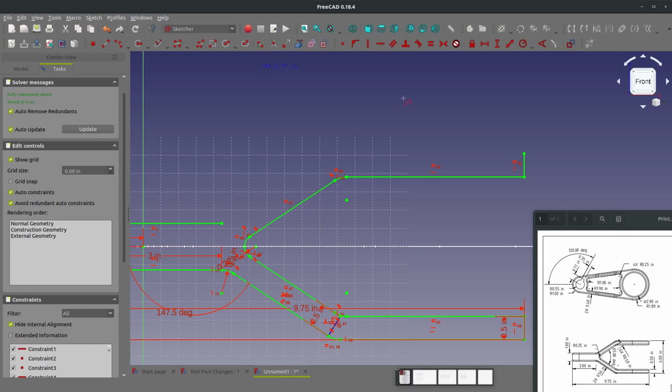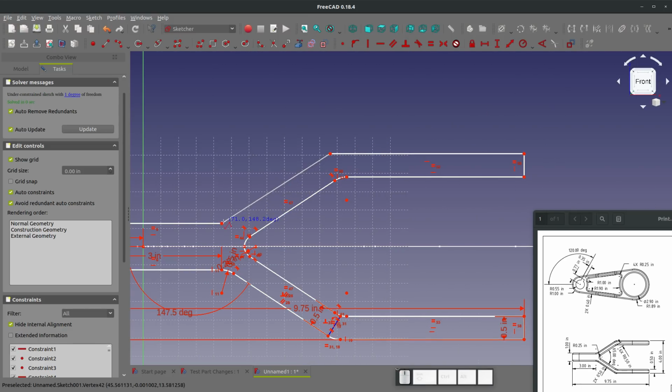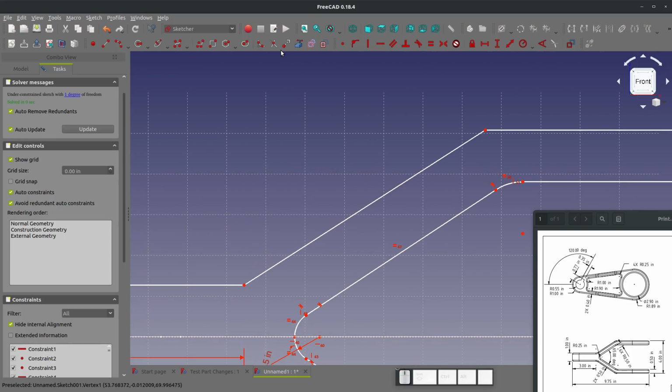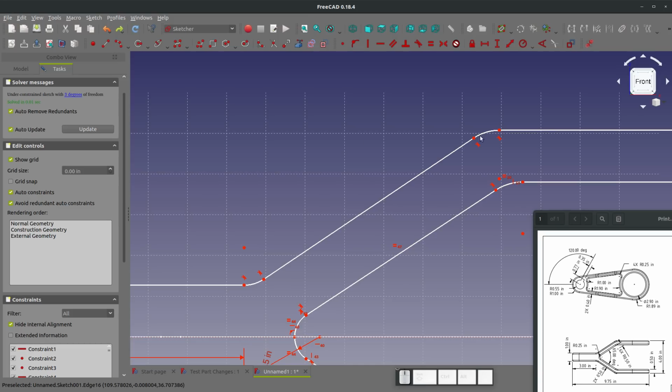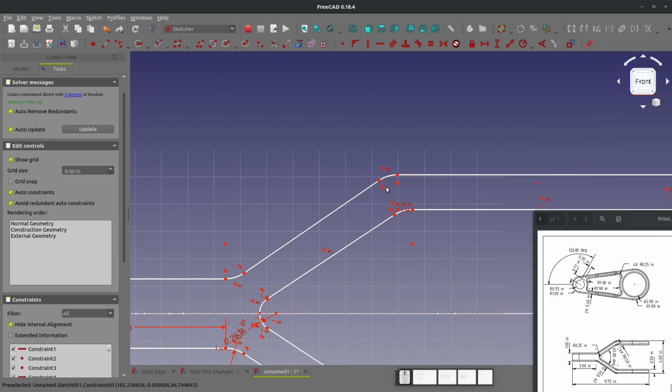Maybe I'll select a polyline over here, right? And then I can choose my sketch fillets. Always fun to add. Select these guys, equal. Looks like we have an over constraint, so we'll Control Z, and I'll just do this one at a time. Equal looks good. Equal.